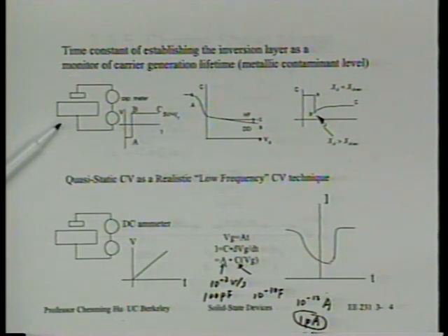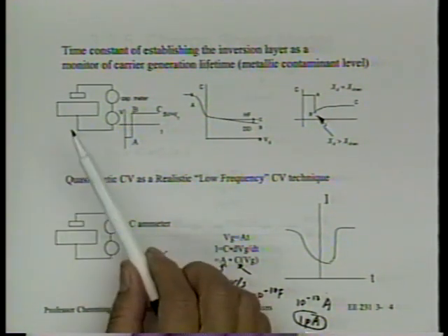Okay. So you always just take a very simple substrate, and maybe with oxide, you may have a poly gate at that time. If you don't, you just put down some simple metal dots as the gate. They can be fairly large dots. You don't even use lithography. You just use something called a shadow mask, meaning it's a piece of metal with small holes drilled through it. You put that mask on top of the silicon wafer, or between the silicon wafer and the evaporation source. So you will get some metal dots on the silicon wafer, and that becomes your monitor.